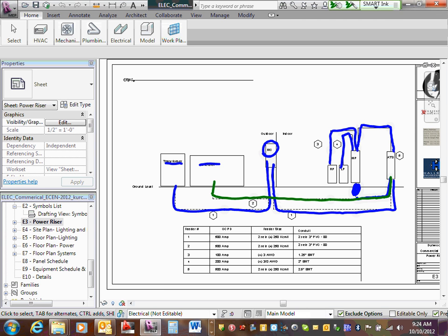And then, like we said, Joe, then you have to have a feeder schedule right here that identifies each number, what size of each feeder, the size of the conductor, number of conductors, the insulation, as well as the conduit. Does that make sense? What you guys are going to be doing? So it's not really that complicated, this project. No, it's not. Yeah. It's a pretty basic, simple riser.